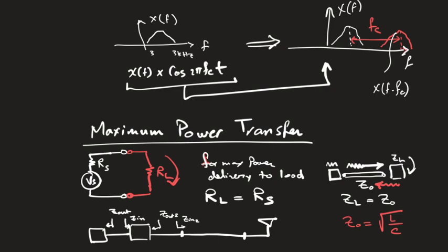As you go through, the output impedance from the previous stage collectively has to be exactly the same as the input impedance to the coming stage collectively, right? Now, in order to make this easier and practical, what happens in the market is that if you go and buy those components, you will find that each one of them has an input and output impedance which is 50 ohm.